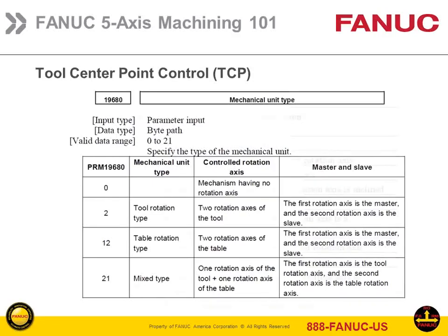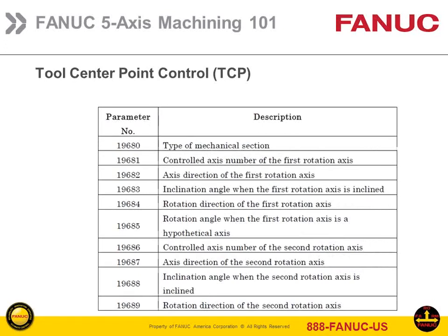Okay. Then we also have about 20 parameters here in the next 2 pages that you have to check. When you're doing this type of machining, when you first install the machine, whether it's a new machine or an old machine you updated, it's important that you get some sort of baseline check, so that 3 months from now you can go back and check it. Either you check it or you have us come in and check it. But it's critical that you maintain that quality, because some of these parameters will affect your part quality.